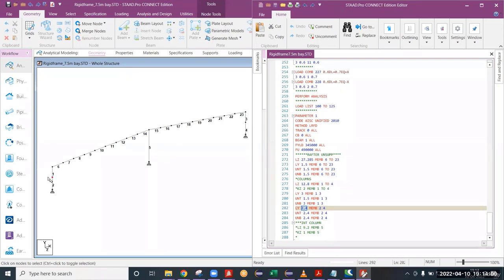So what is the girt spacing? Here we have considered a maximum of 1.5. You can take 1.5 for LY, UNT, and UNB as discussed last time, right? Why have we taken LY, UNT, UNB? Do you guys remember, or should I tell you again how I have taken LY, UNT, UNB values, the unsupported length values? Yes, sir. Because of flange bracings and purlins.